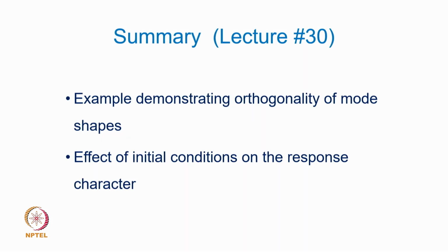So the summary of this lecture: we discussed an example which demonstrated the orthogonality of mode shapes or eigenvectors as we call them. The effect of initial conditions on the ensuing vibration response characteristic has also been explored, and demonstrated to have a significant influence on the vibratory response that you get. The frequency composition is largely guided by the way you initially excite the system.